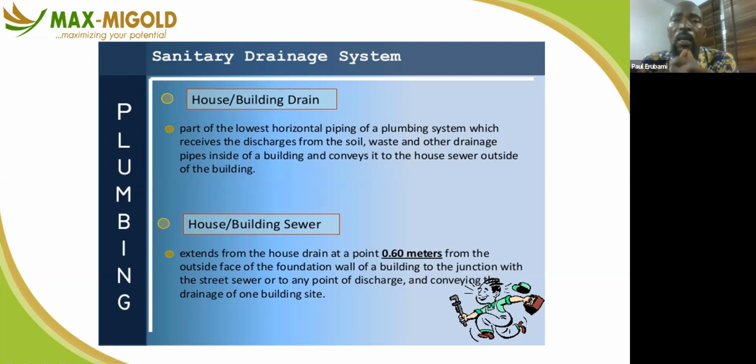Soak-away system is that the entire wall of the sewage tank is not cemented, and that's the reason why they use what we call perforated block when they are constructing it. That is different from on the island, because on the island, the water is already saturated. So you can't use that kind of process on the island, but on the mainland, you can use that.